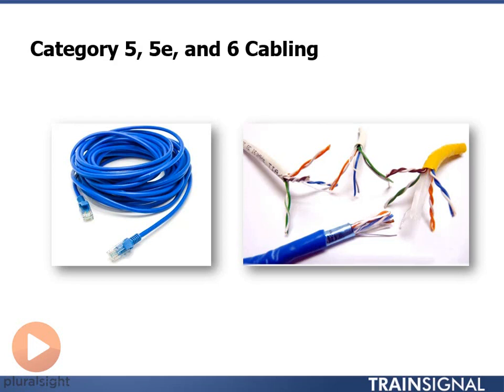So what engineers have done is they've twisted these cables together. They've twisted 2 wires at a time together at a very precise number of twists per inch. What this does is it disrupts the magnetic field that's being generated as electricity is passed through one of the wires. And because it disrupts the field, it's unable to get the signal to jump from one wire to the other wire.